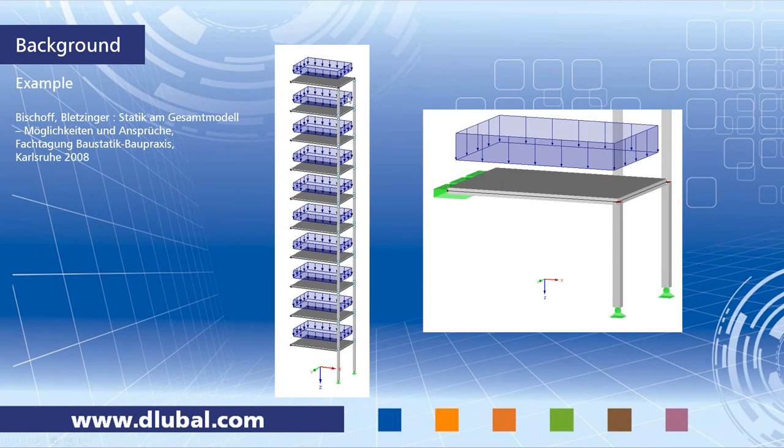And on the outside of the building you see the slender columns, and the simplified structure looks like this. So we have a surface load on the ceiling slabs, we have slender columns, they are connected via hinges, and on the left side it's a rigid line support.